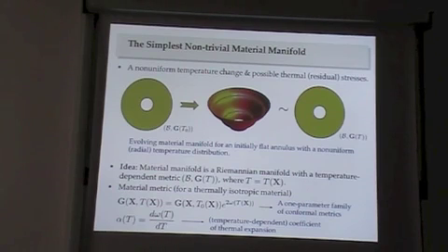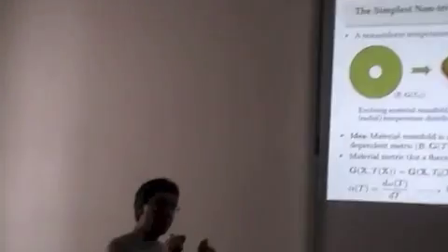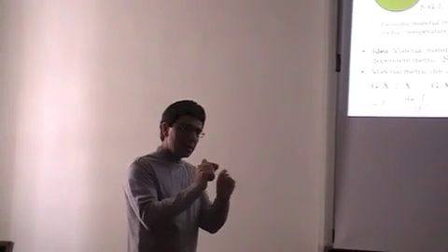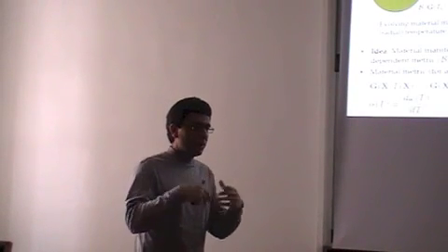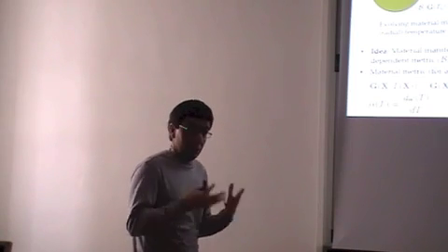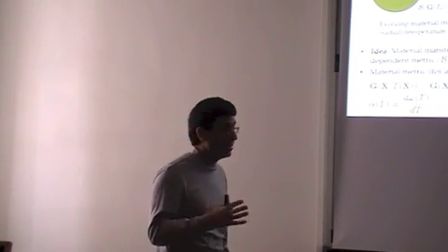Now, this is how I define my material manifold, where I'm stress-free by construction. So why do you induce residual stresses? So your natural distance is from this to a point like this. After I change my temperature, it becomes something like this. And because these natural distances vary from point to point, the rigid geometry of our two-dimensional Euclidean space cannot support that.